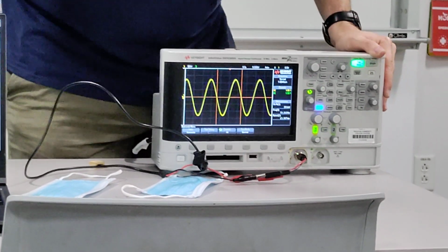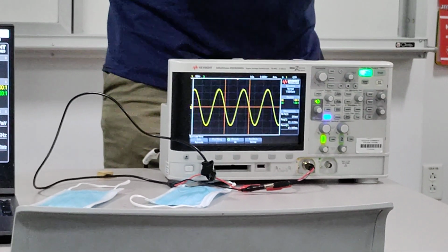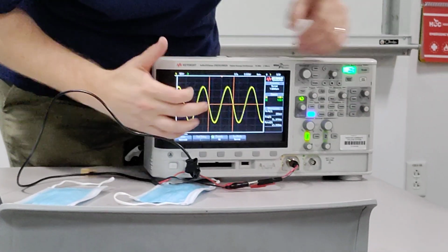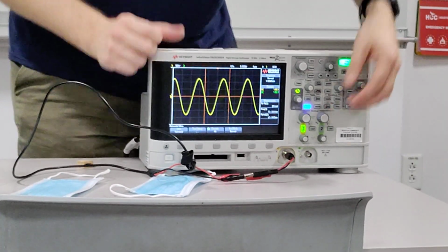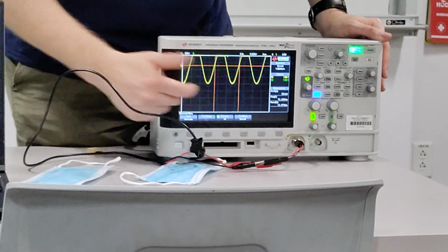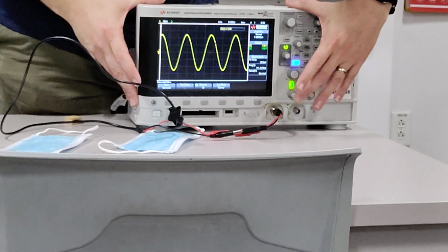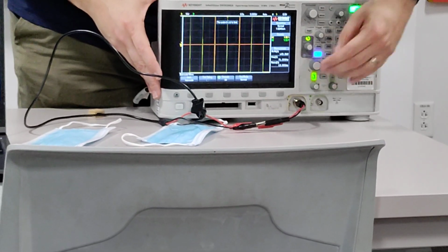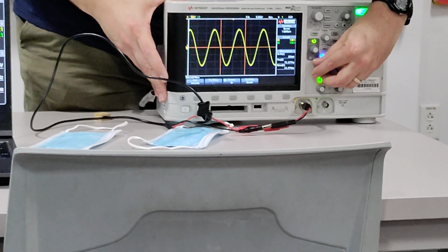So there are reasons, like if you have an AC source and a DC source combined together, you're going to raise the AC source, and you'll have this offset in the signal. If I'm looking at this sine signal and my signal actually never goes below 0, maybe I want to raise it up so it reflects that. So the lowest value is only 0 and it goes up. I've done that now and I've set it up. If I want to go back to the middle, I just hit the button. If I change this to something kind of ridiculous, well, that's not going to work apparently. Thanks, oscilloscope.